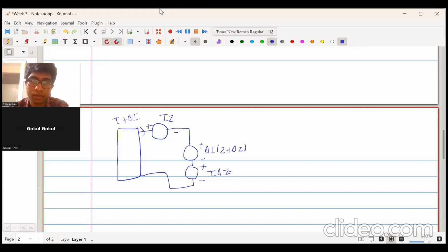So now, like how we proved Thevenin's theorem, we will apply a similar strategy to prove this theorem as well. What we will do is consider this voltage source plus the remaining voltage sources in the network to be active, and these voltage sources are short circuited.